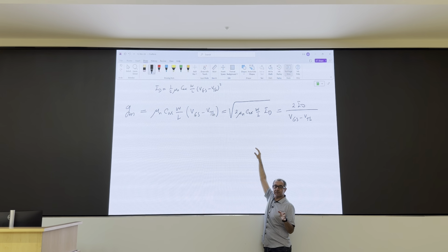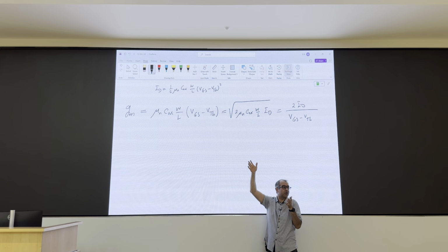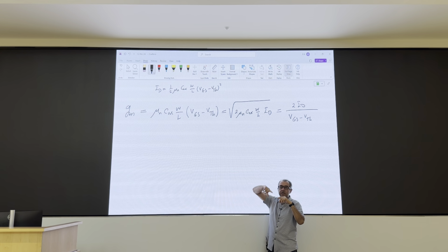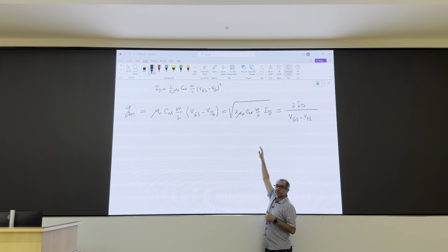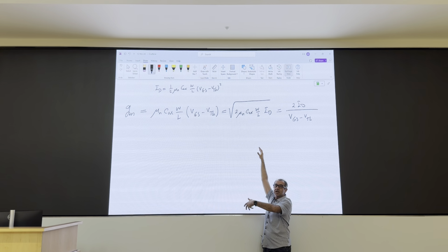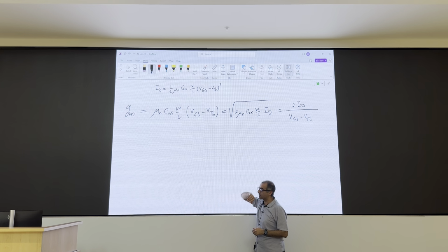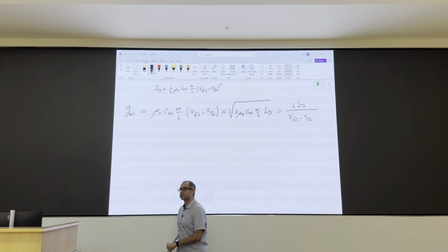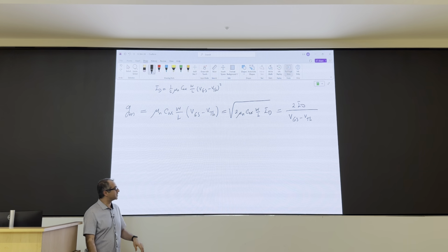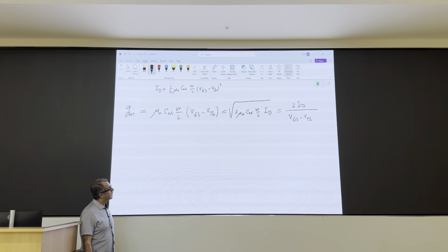Your GM, first of all, that exponential relationship right away means that it is more sensitive compared to the quadratic equation. Quadratic rate changes are slower. Exponential, it's super sensitive to any change in VBE. Quadratic is slower by nature, but you see it here. With the BJT, you double ID, IC, collector current, you get twice the GM, twice the transconductance. For MOSFET, you get a little bit less. However, for MOSFET, you have that size. You can play with W/L and compensate for that to some extent.